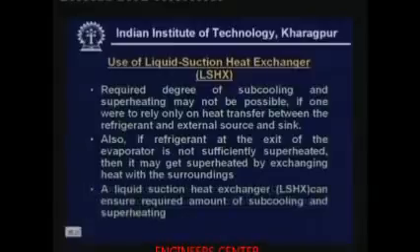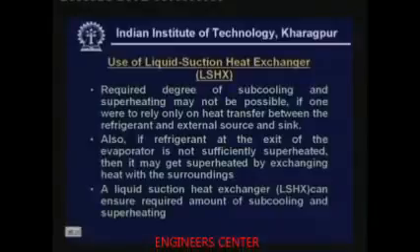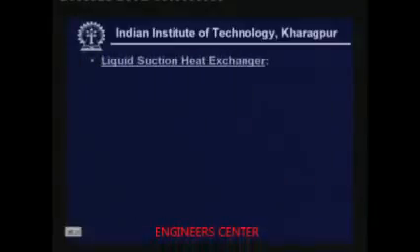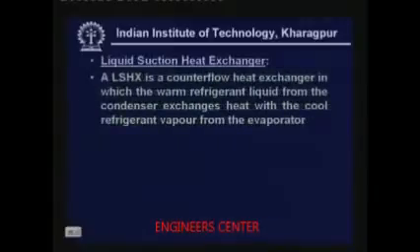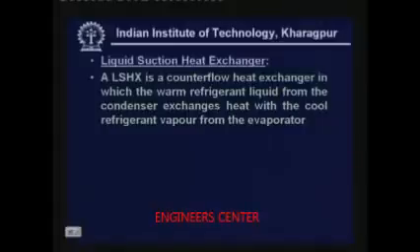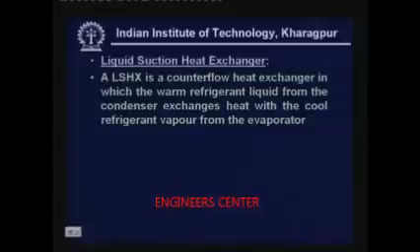So a liquid suction heat exchanger can ensure required amount of subcooling and superheating. Let us see what is a liquid suction heat exchanger. A liquid suction heat exchanger is basically a counterflow heat exchanger in which the warm refrigerant liquid from the condenser exchanges heat with the cool refrigerant vapor from the evaporator. So let me show this.